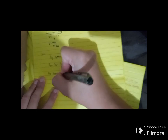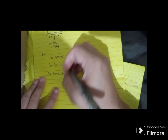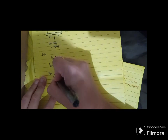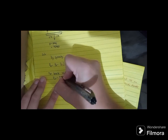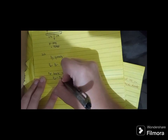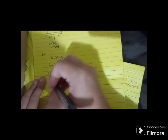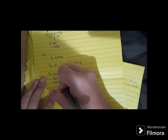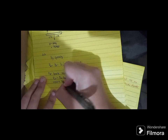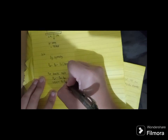For the bronze cable, we use the formula of the stress. So we have P bronze equals stress bronze times area bronze, which is 3924 equals 90 times area bronze.